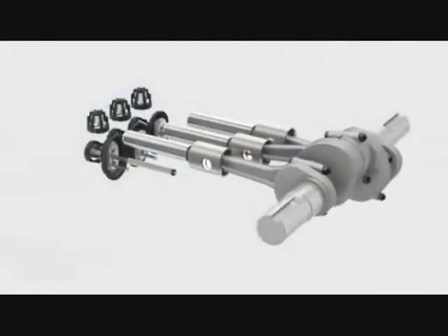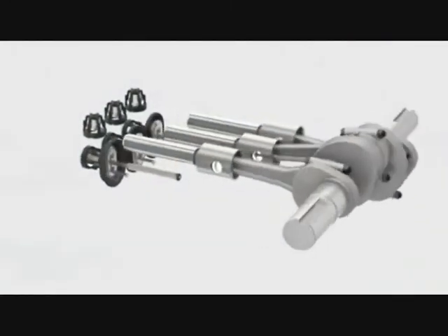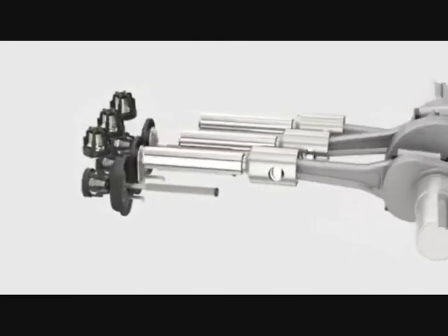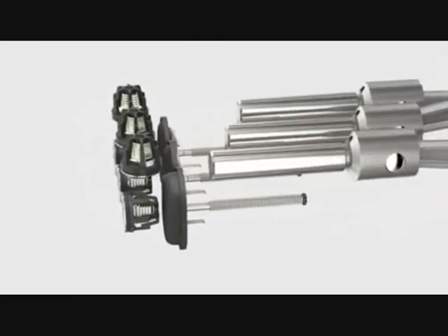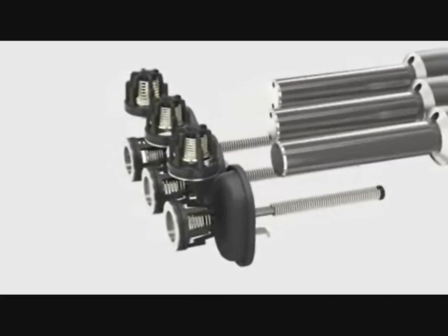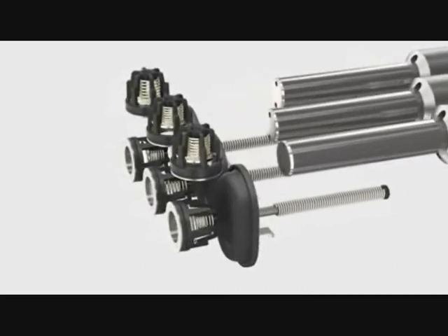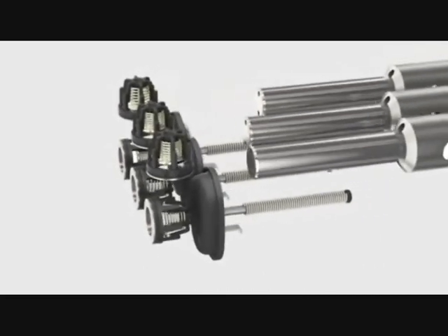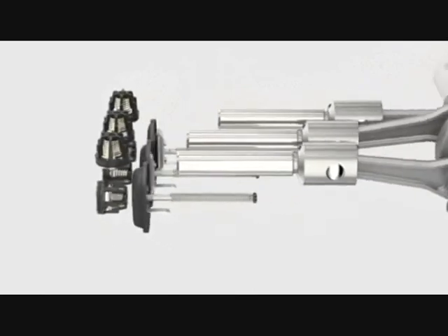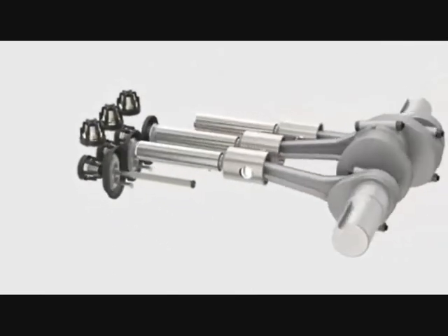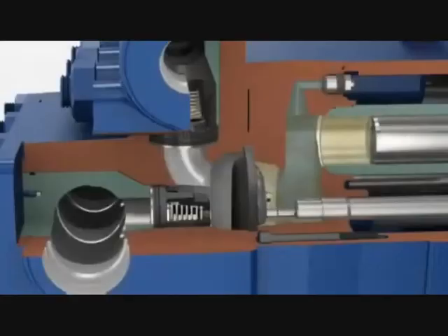The pump's crankshaft drives plungers that hydraulically expand and contract a single diaphragm in each of the pump chambers. Sequential expansion and contraction hydraulically open and close inlet and outlet valves, circulating fluid out of the pump at pressure up to 4,500 psi. The unique and proprietary design of the pump's diaphragm prevents the wear that typically occurs with other types of surface pumps.